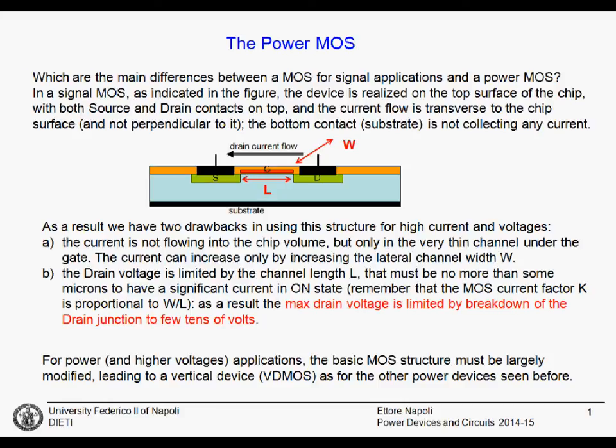They heavily depend on conductivity modulation. This means that the resistance is not the basic resistance of the silicon, but the resistance that you see when a huge amount of carriers is injected into the drift layer. For this reason, bipolar devices also have problems in switching, because all this charge needs to be injected and removed from the device.